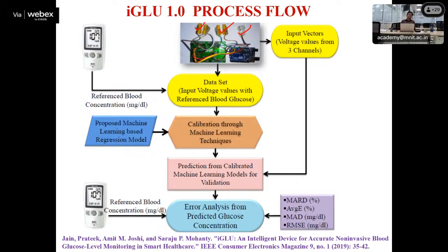So we have used three sensors. 940 and 1300, these are the two possible wavelengths, and for them we have used absorption and reflectance. There is no role of scattering observed over here. But absorption for the two wavelengths, 940 and 1300, definitely plays a crucial role. And the reflectance of 940 also improves the accuracy of the glucose estimation to some extent, so we have used that sensor also. So these three sensors are basically developed.